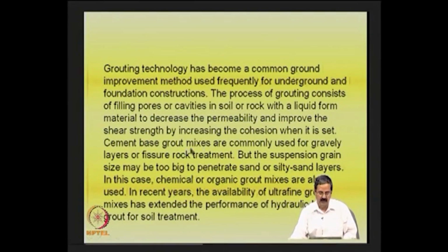The cement based grout mixes are commonly used for gravelly layers or fissure rock treatment, but the suspension grain size may be too big to penetrate sand or silt sand layers. In many cases when you put the grout material, the particle size is very important. Whatever you are trying to grout, it should get into this soil system and then stabilize the whole area.